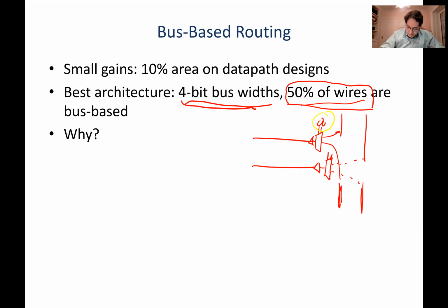So normally this mux would have its own configuration cells, and they're saying, nope, what we're going to do is get rid of those, and instead we're just going to wire his configuration to those other SRAM cells. So yeah, you have to go through and do a bunch of detailed area modeling, and I believe I have this actually on the slide, but the CRAM area is significant, but the MUX area is even bigger. So fundamentally, they're saving some of the area of the routing, but not the bulk of it. So that's going to fundamentally limit how much they can save.